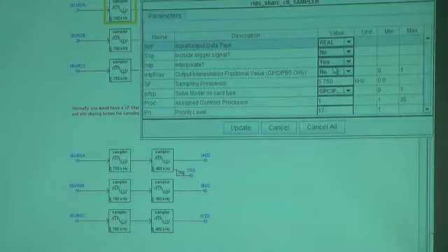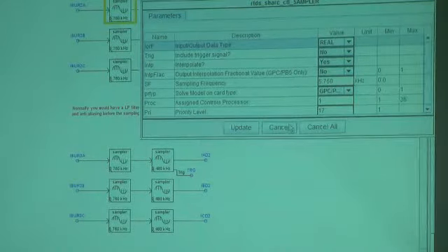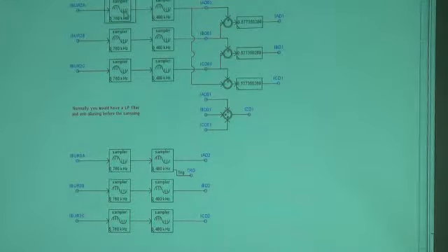So if your sample rate isn't an exact integer of your simulation time step, it'll interpolate and output the correct sample point. So it samples at 96 samples per cycle, and then downsamples to 8 samples per cycle, and then it just ends up creating the downsampled delta currents.